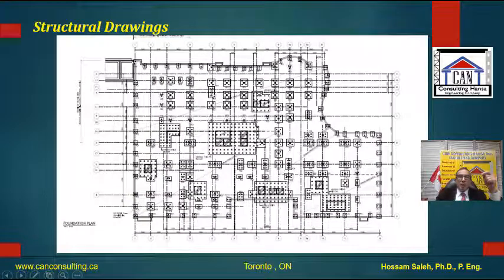Now, if you have pile caps with H piles, you can have a drawing like that. Here, you can have four piles, and then the column is above that. You can have different piles underneath the shear walls, so it can be rectangular. Most of the time, you are going to avoid combining footings together. So here you have to put the orientation of your pile cap to avoid interfering with that.